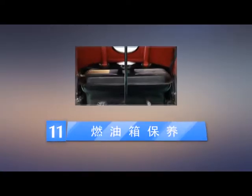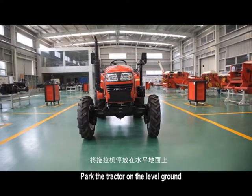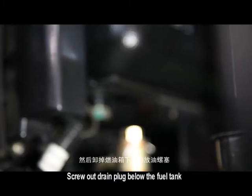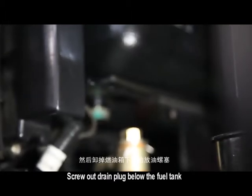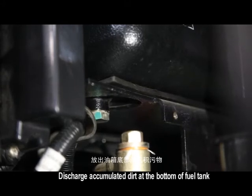11. Maintenance of fuel tank. Park the tractor on level ground. Stop the engine. Screw out the drain plug below the fuel tank. Discharge accumulated dirt at the bottom of the fuel tank.